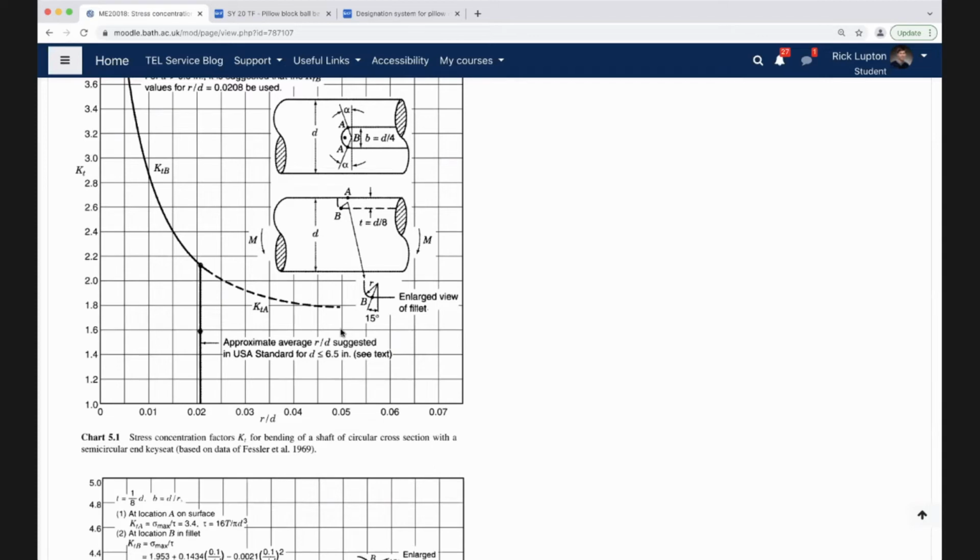Remember that this kind of approach to design is fairly rough. It's about doing that iteration and converging on something. You don't want to be doing a really detailed analysis every time of exactly where the stress concentrations in a keyway are. You want something that gets you roughly right the first time. And then when you converge on a final design, the next step after what we're doing would be to put it into a finite element model, probably, if it was something important that you wanted to check. If it was something kind of bog standard, low stress or low significance, then you'd probably be happy with these calculations, but you could always go back and look at this in more detail.